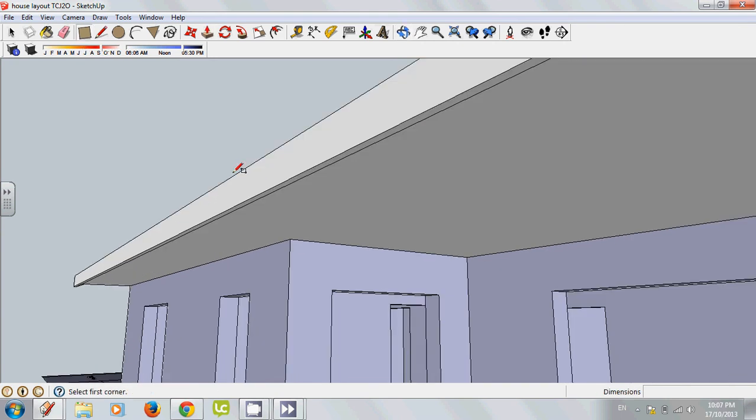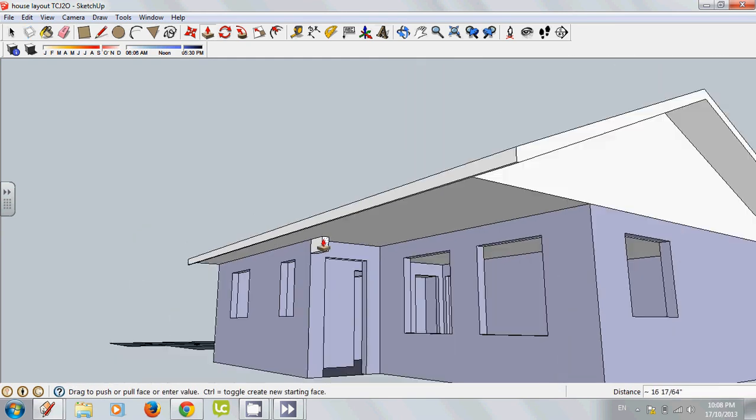So I'm going to put a beam in there and a couple posts actually. So I'm going to come into this corner and I'm going to drag this down and I'm going to put a beam in here that's going to be 10 inches by 5 inches. And I'm going to pull this across out to this surface here.